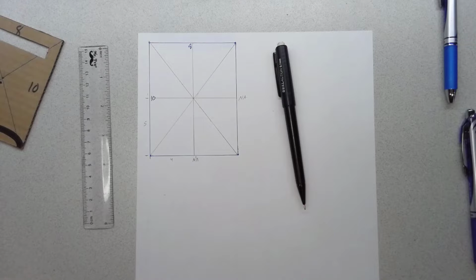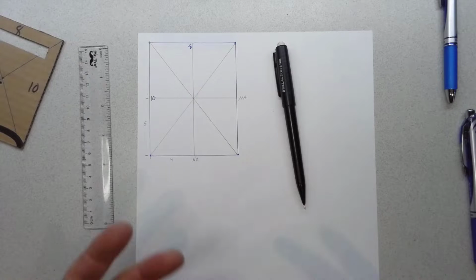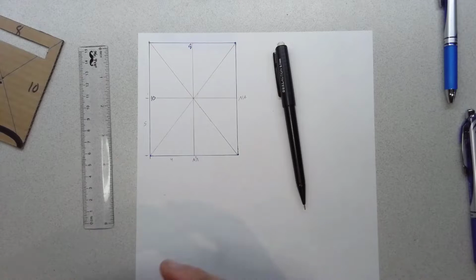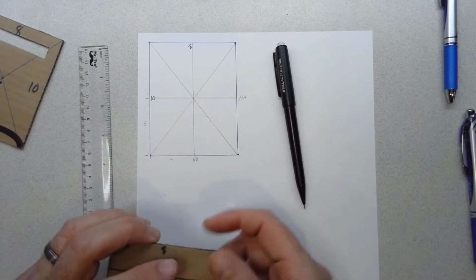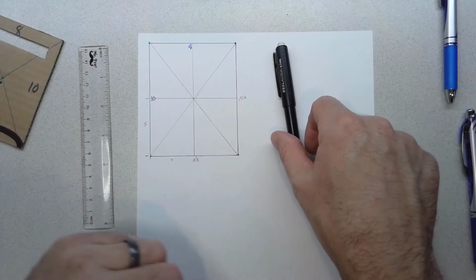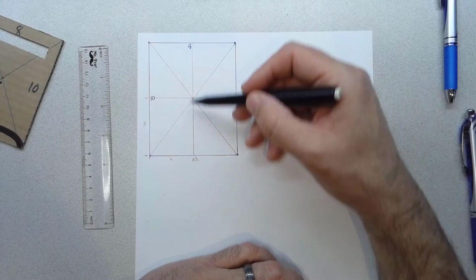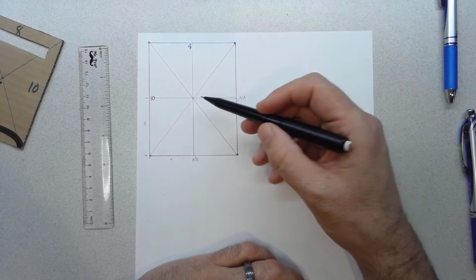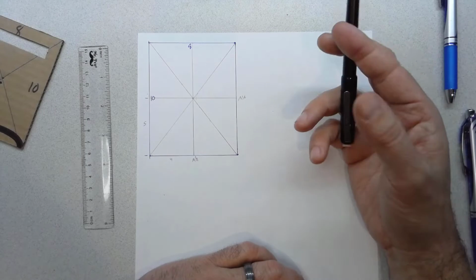As a reminder about that, the centroid of an object, whether it's the center of area if we're looking at 2 dimensions, or center of mass if we're looking at a 3-dimensional volume, that's the point about which all of whatever quantity you're looking at, whether it's mass or area, all of it is balanced. So if we think back to a rectangle, like 2-dimensionally shown here on paper, it's really easy to see the centroid of that. It's fairly intuitive to us, right? We find the axes of symmetry, and where they intersect, that's going to be our centroid.